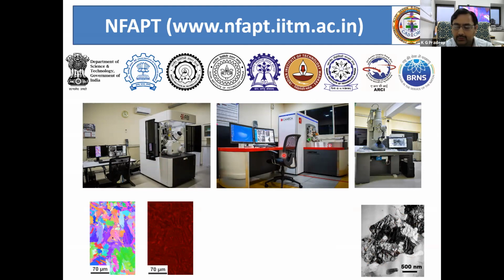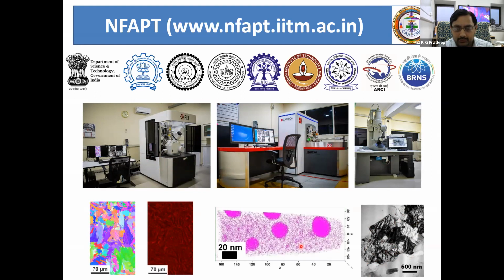The in-between one is the atom probe tomography, where we'll be able to see individual atoms being spatially distributed in a small three-dimensional nanometer scale volume. This is where the interest lies, because in the bulk scale, when you have a few atoms forming a cluster, it may be very difficult to discern this arrangement, and very difficult to understand their local chemistry. This is where atom probe tomography is so important.